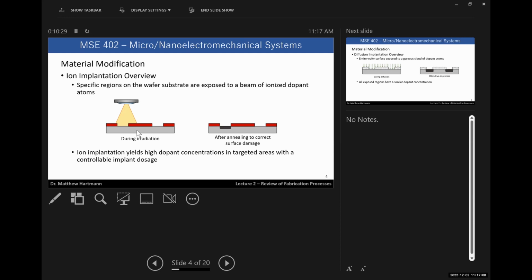So the annealing process, which is carried out at a very, very high temperature, effectively removes all of that mechanical stress from that interface, and it helps to drive the implanted atoms deeper into the wafer surface, yielding a concentration profile, something like this, where we have a region with a fixed concentration of dopant atoms.